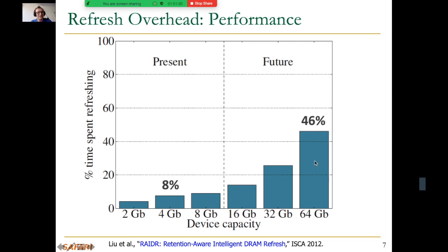I believe actually we're stuck with DRAM for a longer time than people think that we will have DRAM, because DRAM is actually a very, very strong technology, in my opinion. It's very hard to find another technology that provides you the same density and latency characteristics. So it's reasonable latency. Okay, latency is always high, of course, but it's reasonable compared to some other technologies, and the density is very high, and we're using it in very good ways today. So DRAM is going to be around for some time, and it doesn't have endurance problems like some other technologies do.